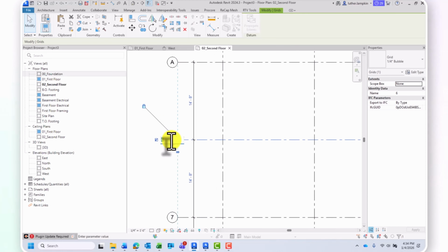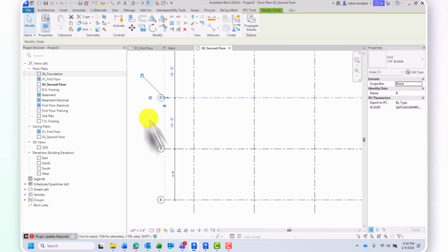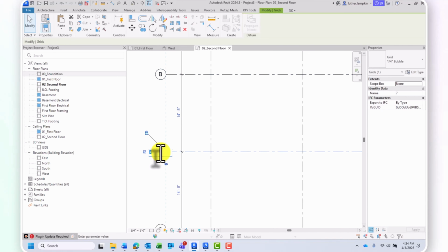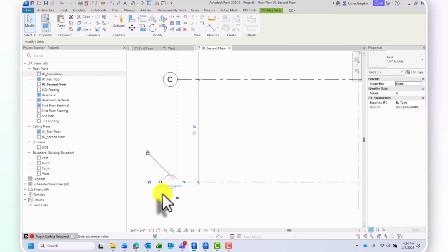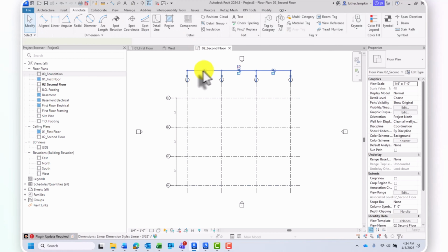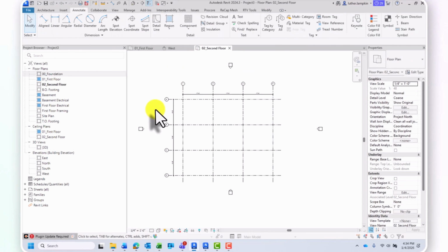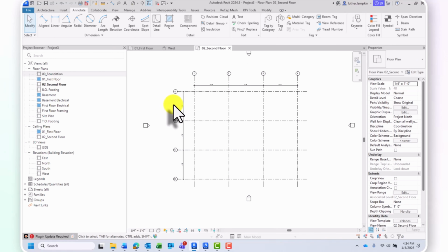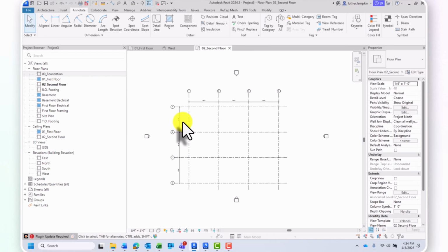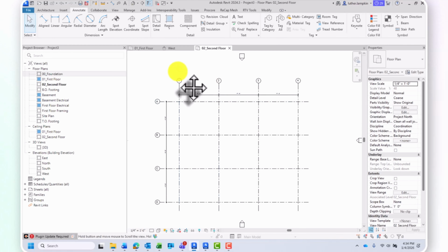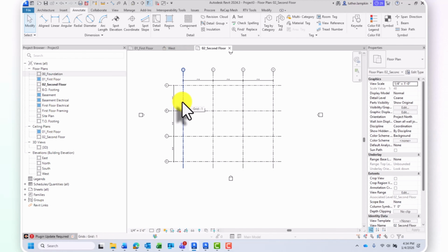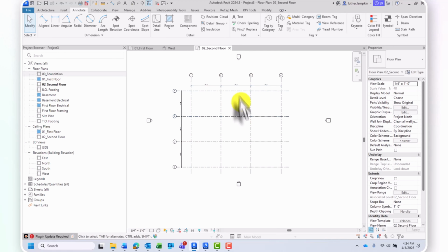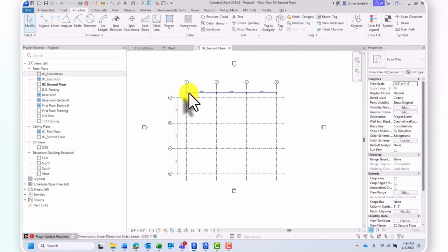All right, you're always going to start all your buildings the same way, no matter what. And this is what you can see, and this is the proper way to do it. You're going to have your numbers at the top, and you're going to have your letters to the left. So this is how you're going to align your buildings, grids and levels and elevations, because this is going to be the start of your project. Super, super important that this is always the base and foundation.